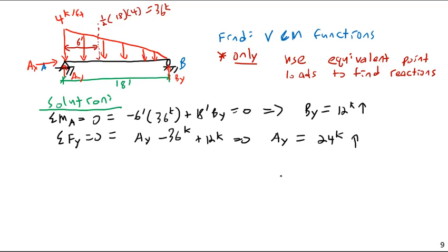So now I have my reactions. Thankfully, on this particular beam, I have no discontinuities, if you notice, except for at the edges. So I can actually get away with using a single moment function and a shear function to describe these things.